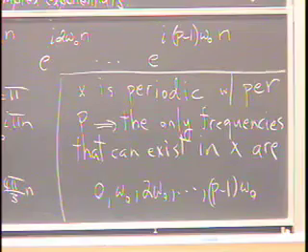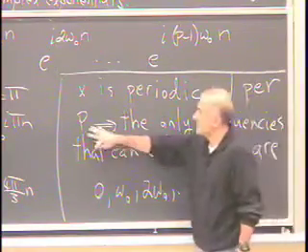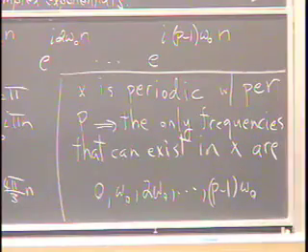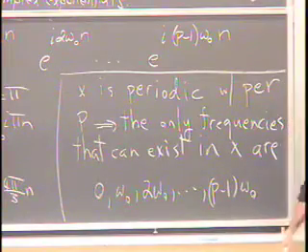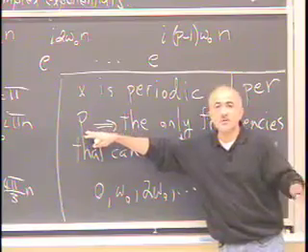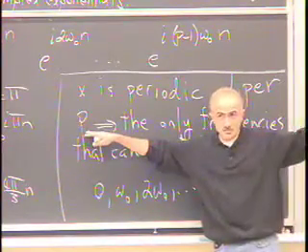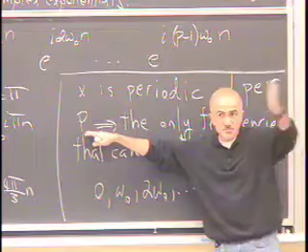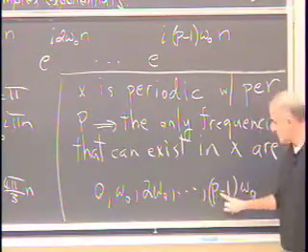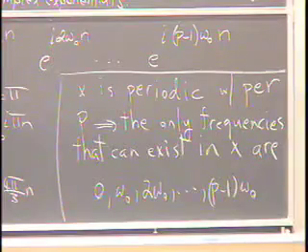You can't have a periodic signal with period P and have, for example, omega naught over 2 as one of its frequency components. That's one of the beauties of Fourier series decompositions. So if you have a periodic signal with period P, the only frequency content, when you look at its spectrum and try to figure out what frequencies are present in that signal, those frequencies appear at a discrete set. It's a discrete set of frequencies.